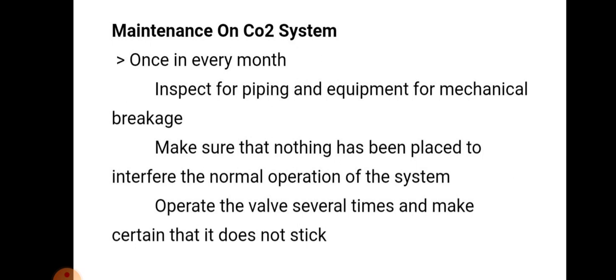Once in every month, inspect for piping and equipment for mechanical breakage. Make sure that nothing has been placed to interfere normal operation system. Operate the valve several times and make certain that it does not stick.